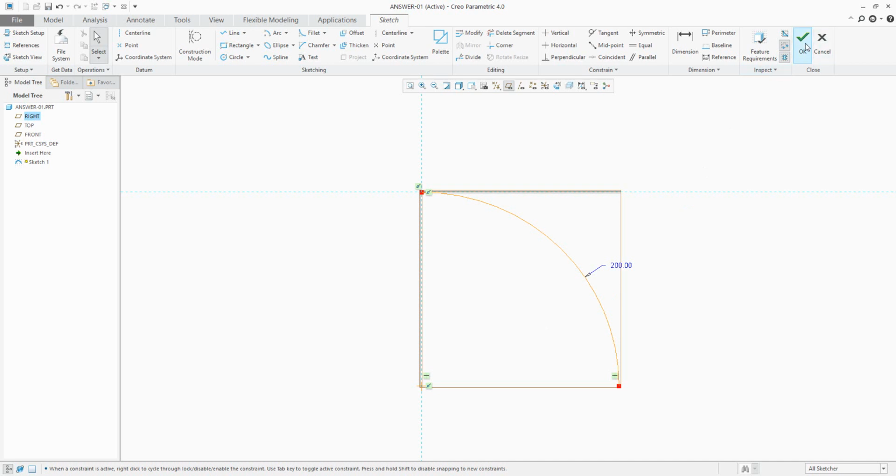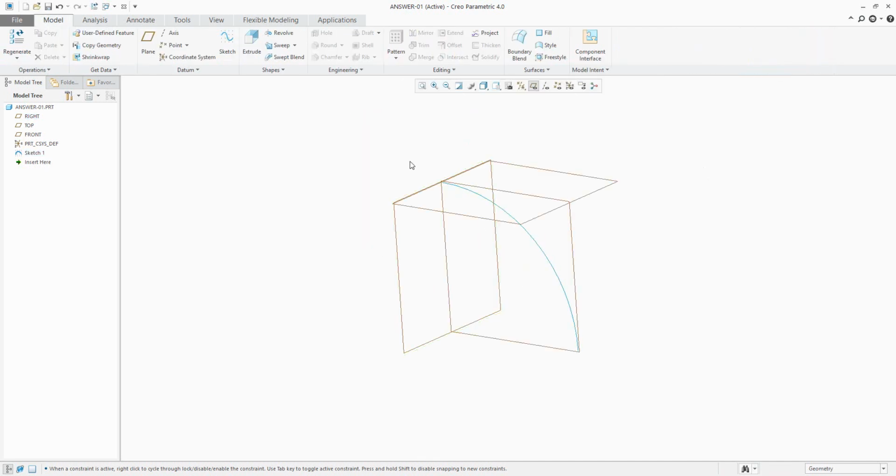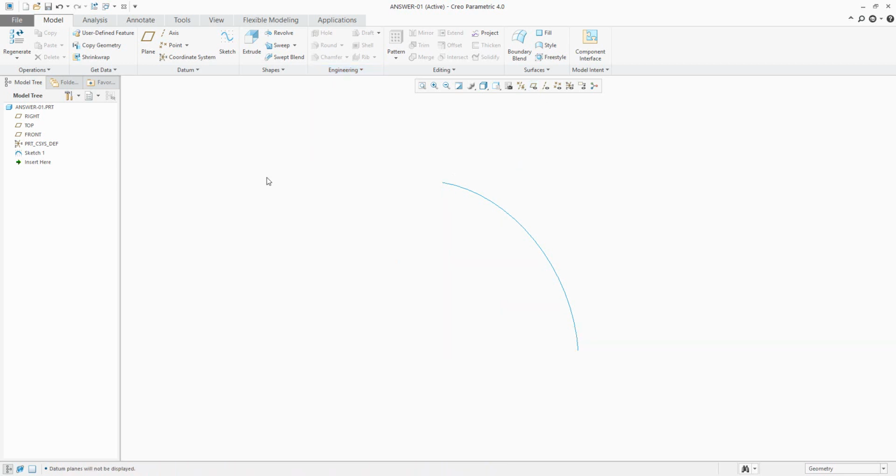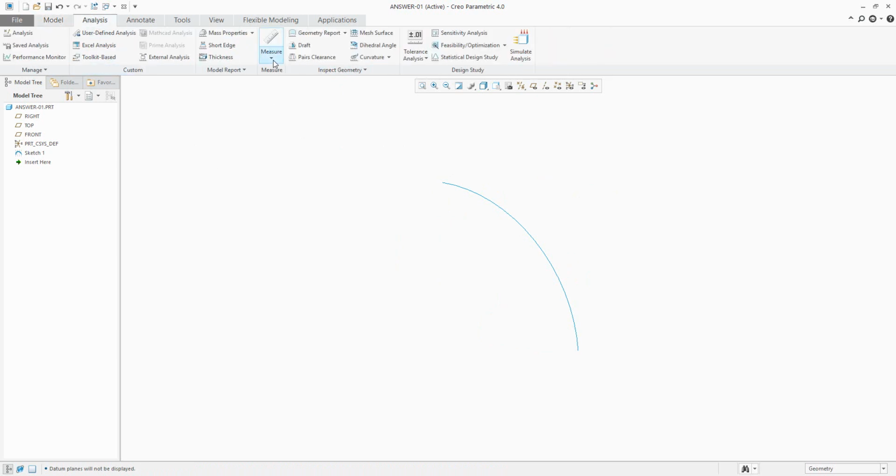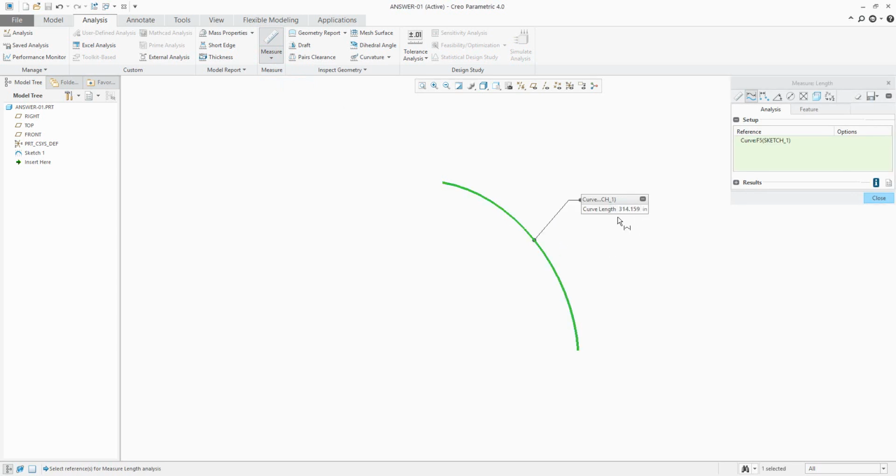Yeah, and you know that if you would like to create the elbow, you can use the revolve feature, you can use the sweep feature, it's up to you. But for now, I'd like to reuse the Spinal Bend feature for this elbow. I will combine it with the analysis. So let's go here to the analyze feature, and I'd like to measure the length of the curve.